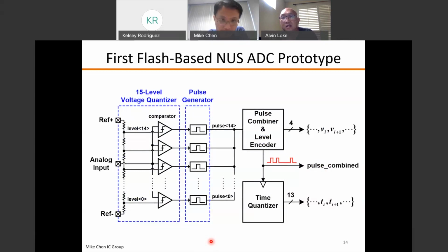Right, that's a very good question. The comparator by itself, indeed, has latency. But so long as everybody has the same latency, it doesn't really matter, because you just delay. You can imagine that all the non-uniform samples just shift horizontally by delta t. The delta t can be 1.5 seconds. But it's being sampled with a corresponding latency, so you're fine, you're tracking that latency. Exactly. But here I do want to point out that the mismatch between them becomes important, as you can imagine.